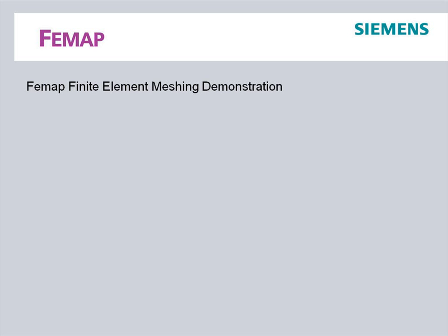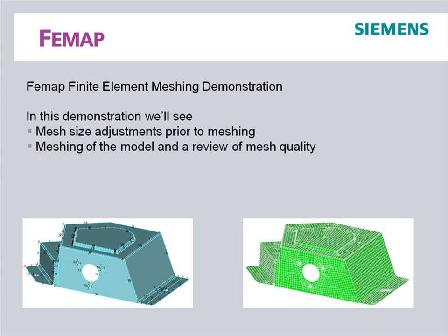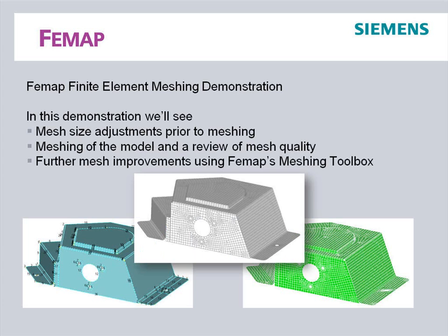Welcome to the Femap model meshing demonstration. In this demonstration we'll see mesh size adjustments applied to the model prior to meshing, the meshing of the model, and a review of mesh quality, and some further mesh improvements after meshing using Femap's meshing toolbox.